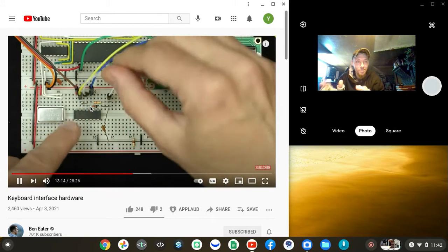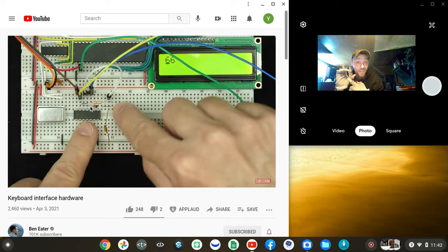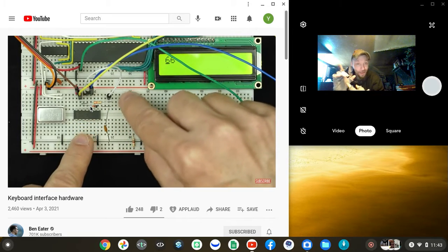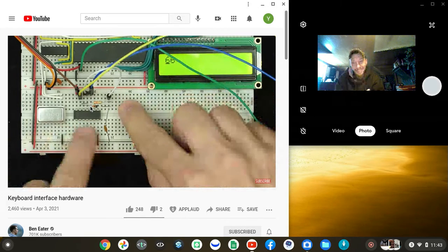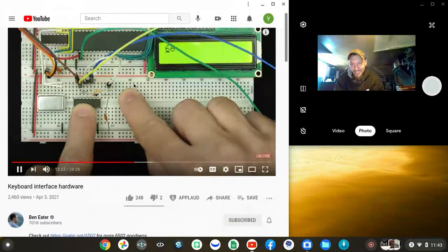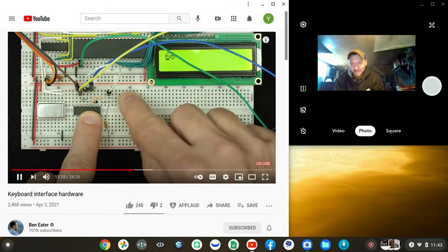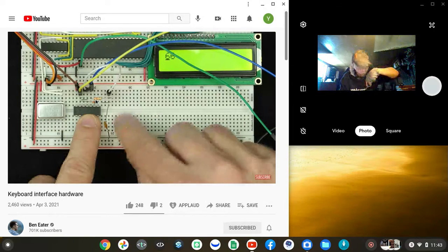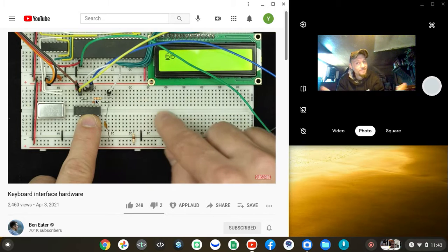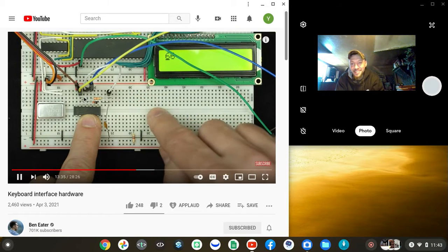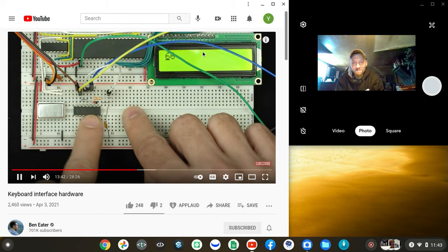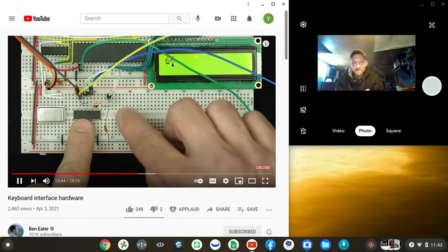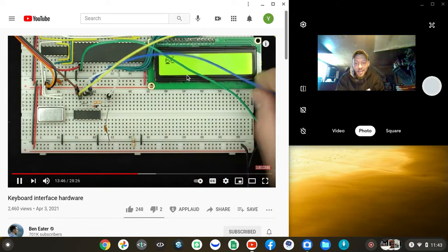What you should see happen here, I think, would be that, first, as the signal gets closer to the 5 volt territory, this inverter should sense that as a high signal and send the output low, and it should be a definite low because this is a digital inverter. And at the end of the pulse, when this starts to tail back down to 0, at some point it'll cross some threshold, and it'll detect this input as low again, and then the output should go high. And so hopefully by running it through the inverter again like this, that should convert this sort of analog-ish signal back into a nice digital signal.